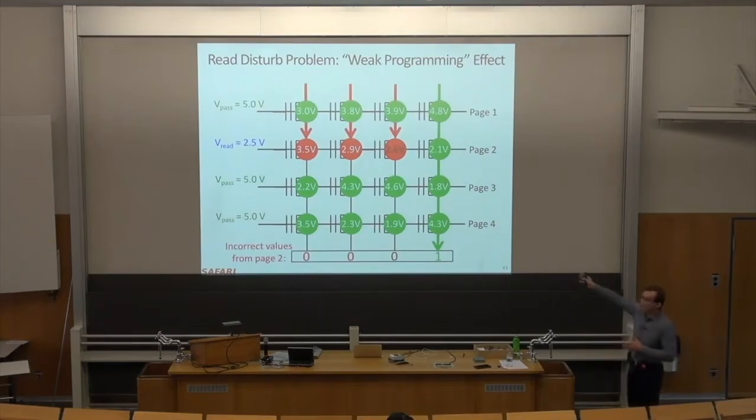And in this case, the read disturb problem actually is worse because you're affected by not just your immediate neighbor, you're affected by anything that's read in this particular block, right? Any page that's read. Because whenever you're reading a particular page, you're applying a very high pass-through voltage to all of the other pages in the block. That's how it works. That's how it's different from the RowHammer effect in DRAM. It's a different error mechanism.